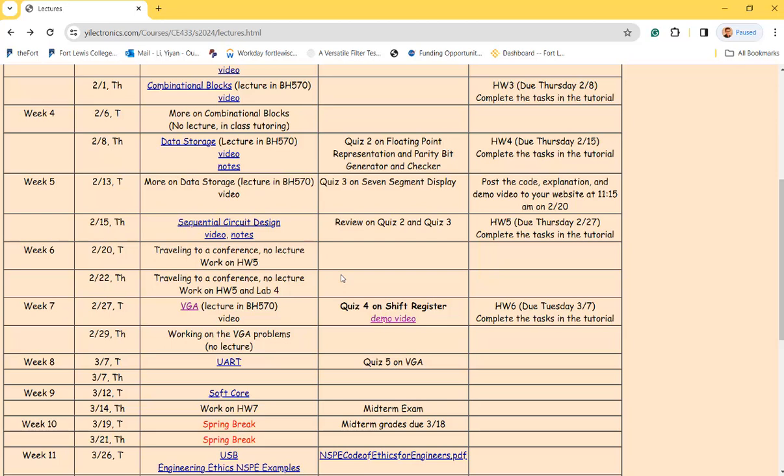Why do you have debounce for switch 1 but not switch 0? Because it's constant data. It's on, then it's on. Your finger is so slow, it's not moving like a flash. You turn it on, and it takes a while for your finger to move to switch 1. It's a state, it's holding there, and it's waiting for the rising edge. If you don't have the rising edge from switch 1, it's not going to do anything. So even though it's bouncing back and forth for switch 0, it's not a problem.